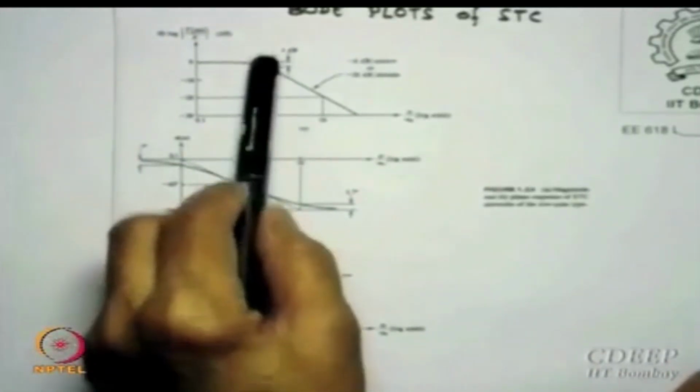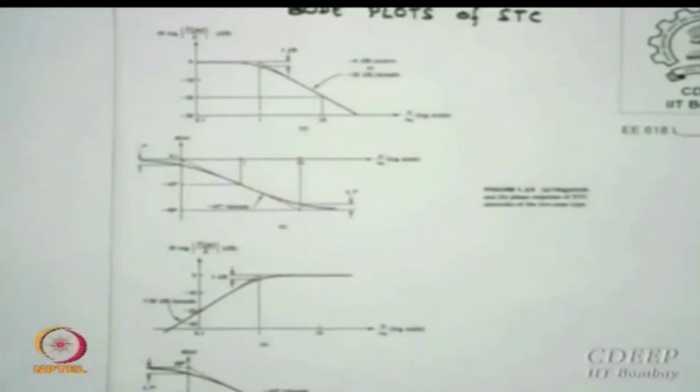Okay. However, what Bode said, extend it up vertically, put a horizontal line, and wherever this intersects he called it a corner point or corner frequency. Okay. And then he started saying, okay, instead of using 3 dB points, use corners. Okay, because anyway you are not going to evaluate from this, what you are going to see is where is the frequency at which gain starts falling.